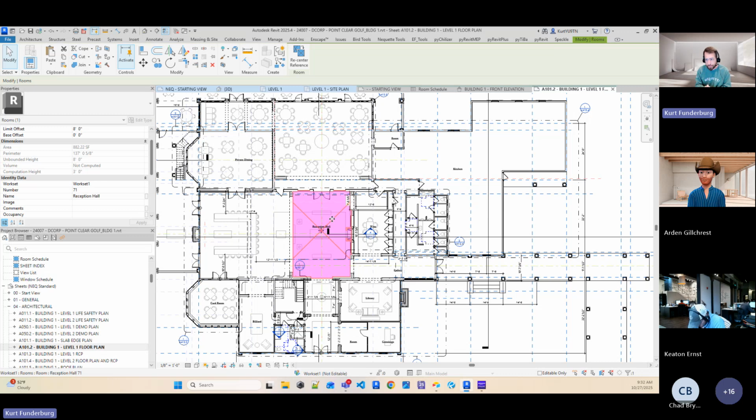They're very versatile. There are some downfalls to room separator lines for anyone who has worked in multifamily where we were using groups. We were using a room separator to define the exterior of the unit, since we don't do the exterior walls in some units. But the ability for Revit to use room separator lines can make wall joins problematic.